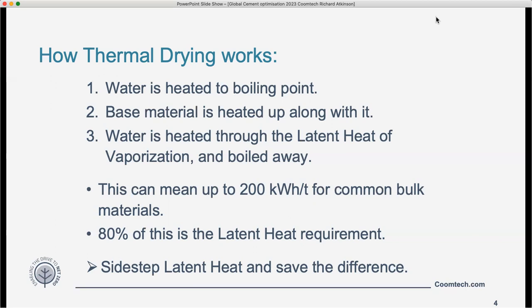So within the thermal drying paradigm, there is definitely optimization work to do, but it tends to be of the care and maintenance variety. You must continually make sure that the internal surfaces of your dryer do not become caked in an insulating rind or crust of material. This will act like limescale in a kettle as a drag on the system, slowing throughput and increasing energy demand. You need to regularly check that you do not have faulty steam traps or other heat loss faults that can cause the system to bleed away heat energy, often undetected. But these efforts can only get you to the theoretical minimum, and that minimum is still high.